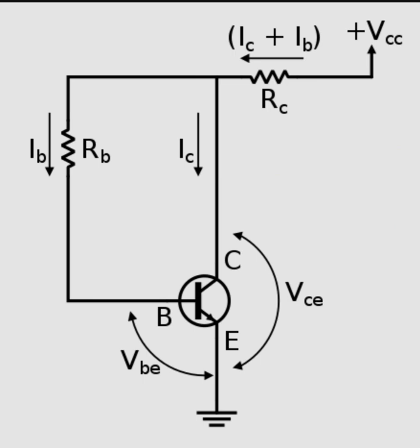The second factor: the transistor has a beta. If this transistor is replaced in the circuit, it will have another beta. Higher beta will give rise to higher collector current and therefore higher base current.